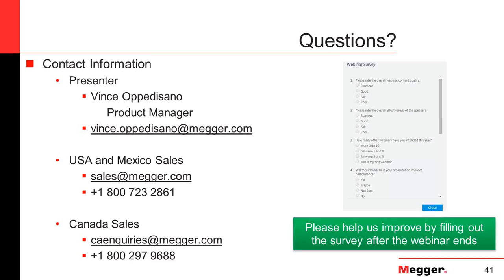Ryan wants to know, is there a temperature standard that we need to cover during resistance? According to the standards, if necessary, and if we want to compare trending, we correct the windings, and I've seen two standards. One is 75 Celsius, the other is 85 Celsius. In all of our instrument forms and in our automated testing, we provide a checkbox that corrects or does not correct the winding resistance. Regardless of the correction, typically we're looking for the curve, and the curve gives us the critical information we use to decide whether that winding, or that transformer, can go back into service for the next 1, 3, 5, or even 7 years.